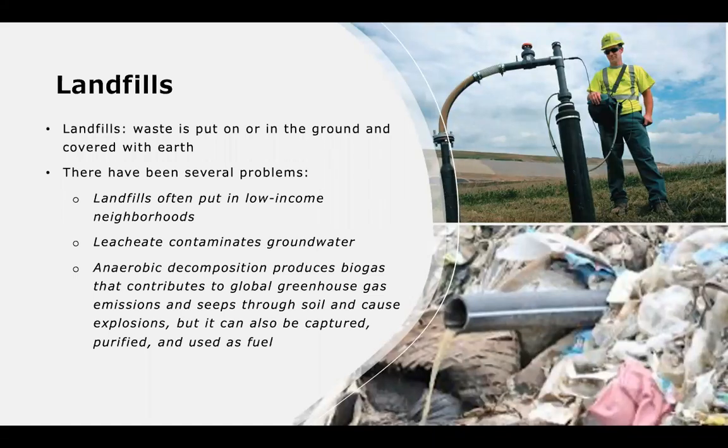Another problem associated with landfills is that the waste decomposes anaerobically, which produces a biogas that contributes to global greenhouse gas emissions, in particular the emission of methane. This methane can seep through the soil. It can also cause explosions. However, if designed properly, landfills can be set up to capture, purify, and use the methane as a fuel source. So there are opportunities there for resource recovery.